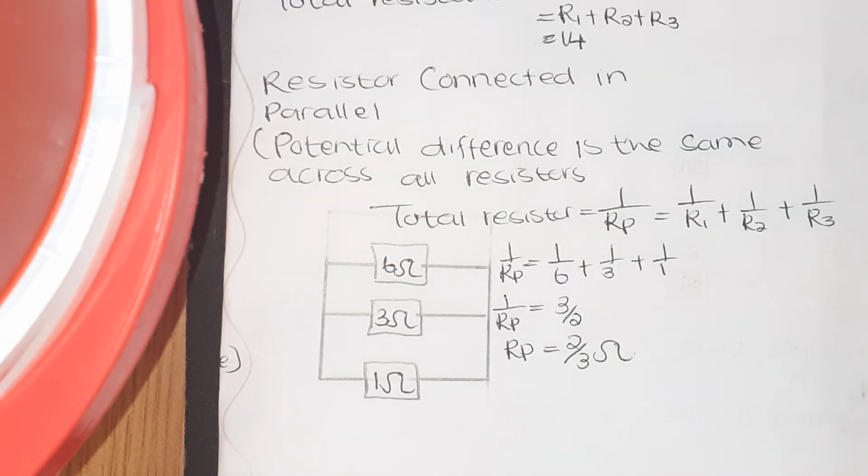All right, now this is a resistor in parallel. Potential difference is the same across all resistors, meaning voltage is the same across all resistance. Voltage is the potential difference. Now we will do it. Don't worry. Resistors are in parallel when they are connected between the same two nodes. This means that the voltage is the same across all resistors, but the current is branched out and recombined.